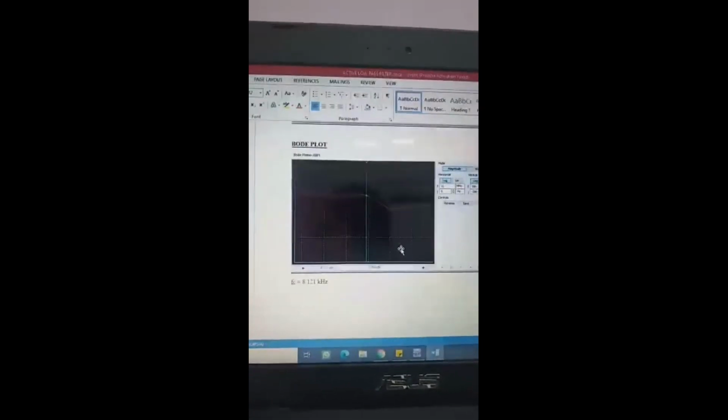From the Bode plot, we can identify that the frequency response curve drops at the cutoff frequency. The cutoff frequency is where the response drops by negative 3 dB from the band pass. This is the band pass. In high voltage gain, when the input signal is at low frequency, the signal will pass through the amplifying circuit directly.